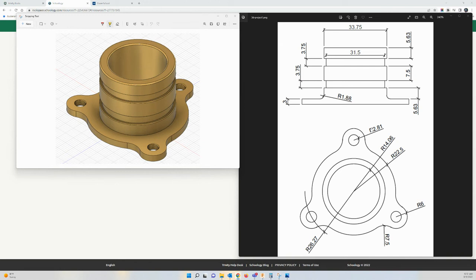We have a radius provided to us, not a diameter. We need to know the diameter to create the circle in the sketching tool. If the radius is half the diameter, then we multiply the radius by 2 to come up with the diameter. So our outer circle is going to have a radius of 22.5 millimeters. 22.5 times 2, that's 45 millimeters.